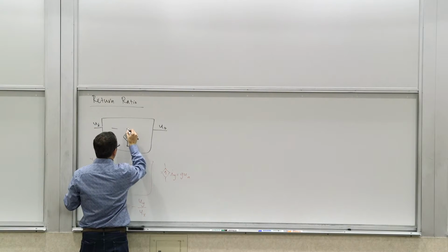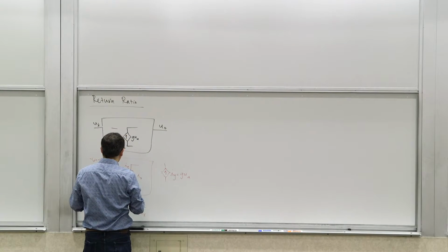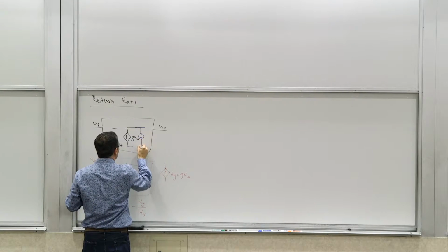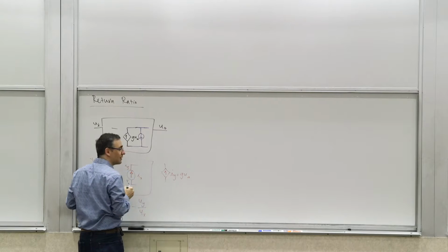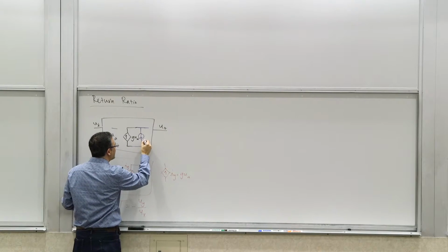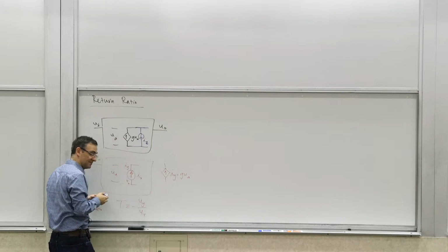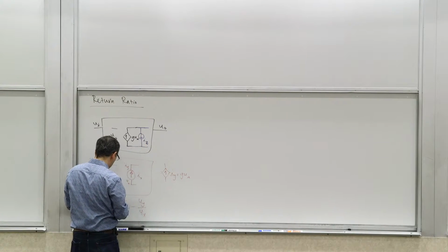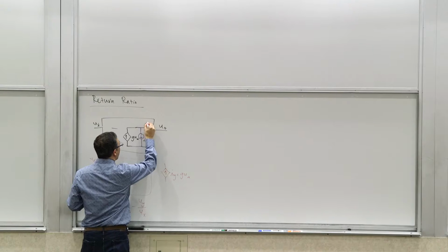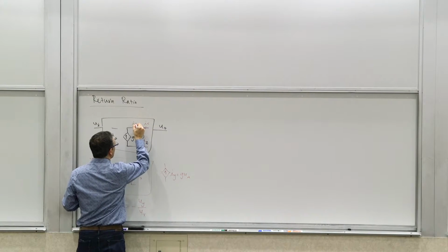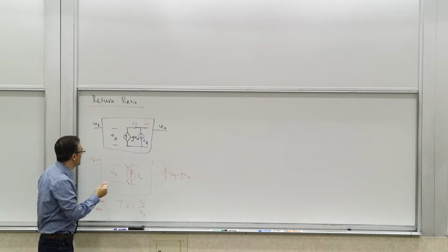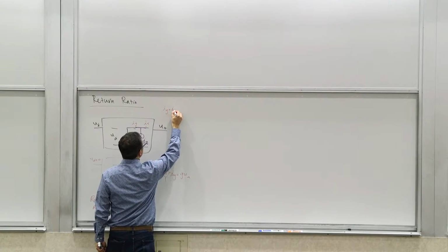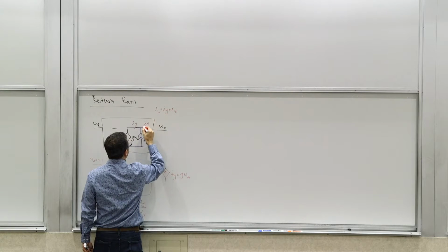What we would do is introduce another current source exactly in parallel with it and call it Iz. This current we call Ix, and this current we call Iy. We know clearly that Iy plus Iz is Ix, from KCL at this node.